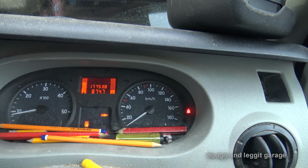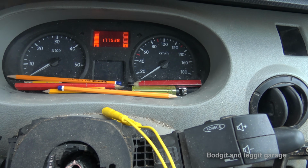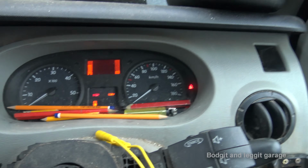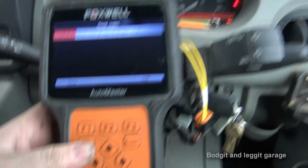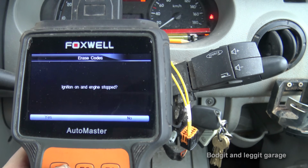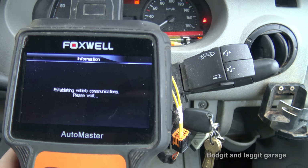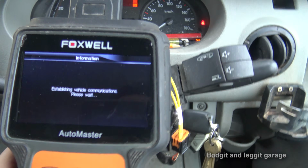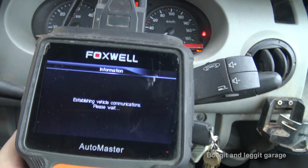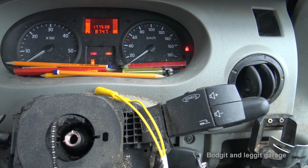I'm sure if I reset the system, well, we can do that. So let's put the ignition on. It's so difficult to do this with one hand. Let's go back out. Let's go to erase fault. Ignition stopped. Enter. Yes. Now, done. If I go back up, read faults. No faults found. Let's just turn this back on.